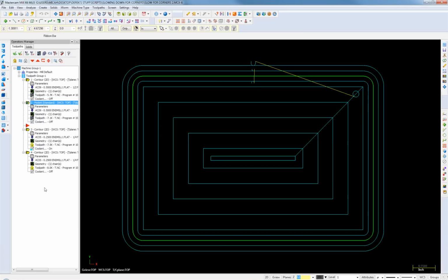Yes. A big key in the older machines, on 2D milling like that, is to filter it pretty loose when you're roughing and make sure you have the XY arcs turned on. Okay, well, can you walk Micah through that? Maybe he can show that on the screen. Pick a toolpath there, because that should work not just in a dynamic core, but on a regular pocket toolpath. Would you agree? Well, you could open up the pocket toolpath.